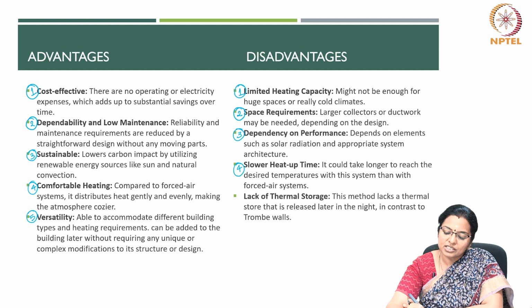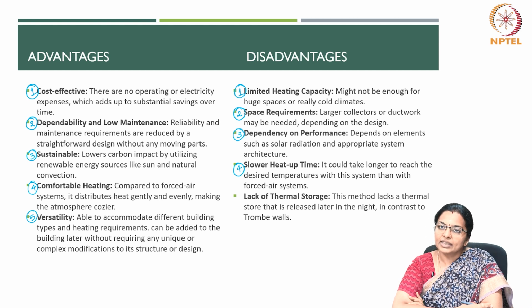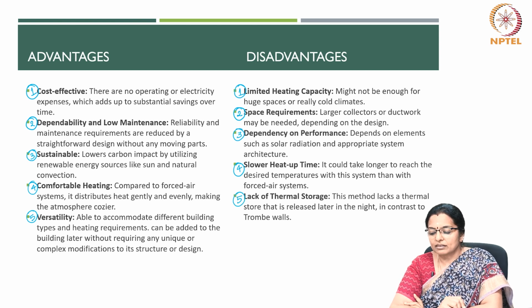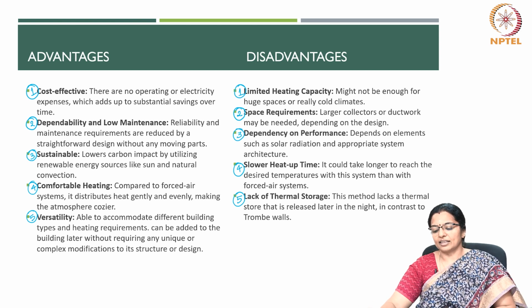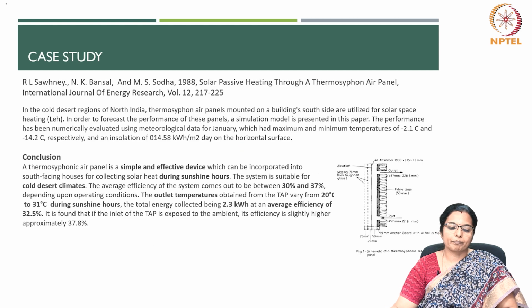Fourth is its slower heat up time. It could take longer to reach the desired temperatures within the system than with forced air systems. And fifth is lack of thermal storage. This method lacks a thermal storage that is released later in the night in contrast to the Trombe wall.